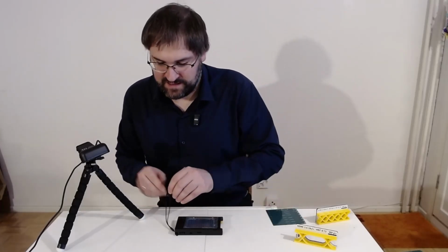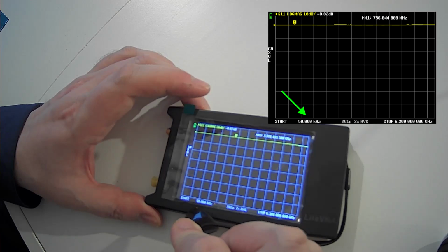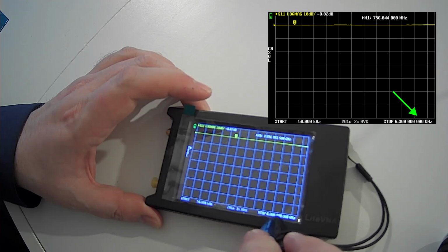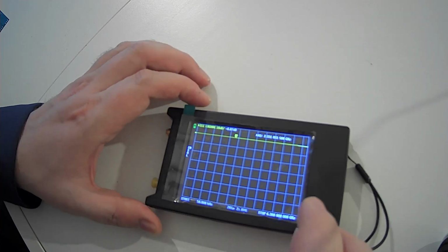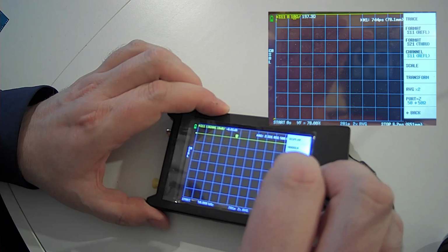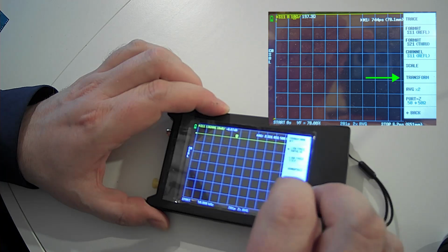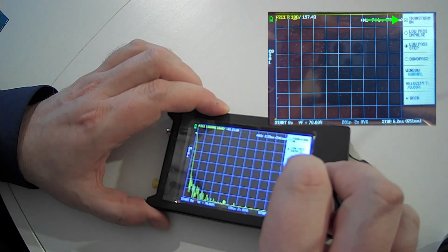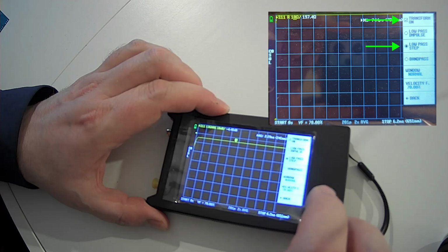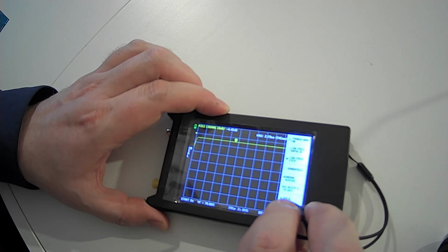So let's first set up the VNA. Make sure that you start at the lowest possible frequency, and for best spatial resolution use the maximum bandwidth of your device. To get the visualization, which you would also get from a TDR measurement, first go into the transform menu, enable the transformation and set it to a low pass step function. So this will correspond to the step function of a TDR measurement device.